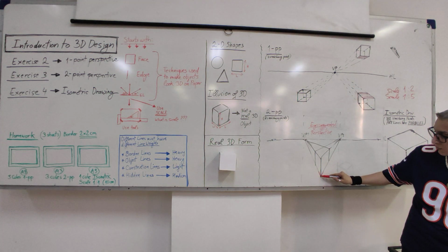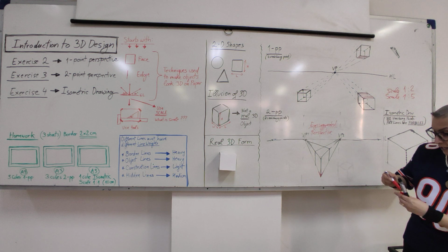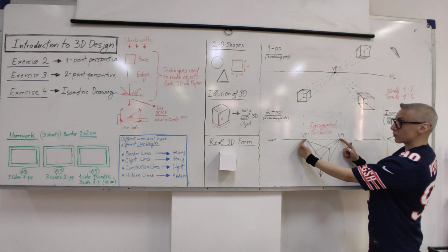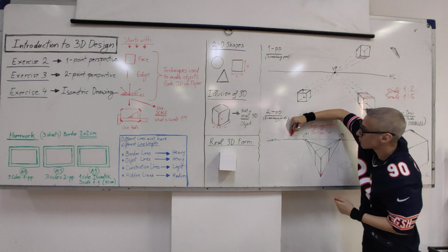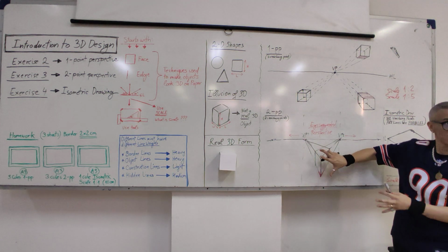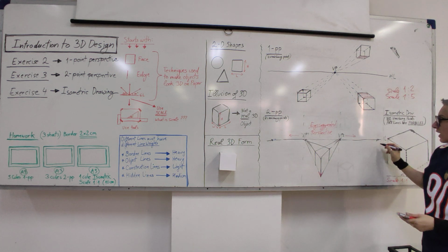When this happens, like this corner, it's very sharp, and even this corner, it means that the object is too big for these vanishing points. That means you need to take the vanishing points and put them further apart. If you want to do this size, you need to put them farther away, and then do it.